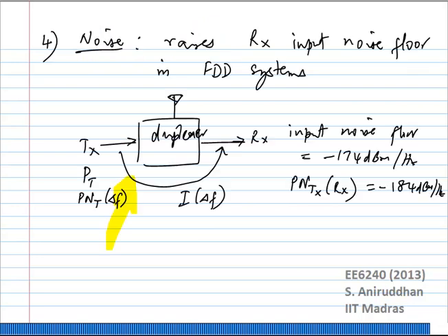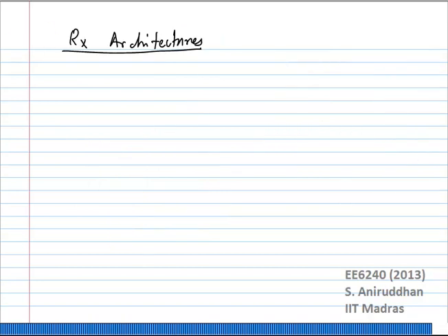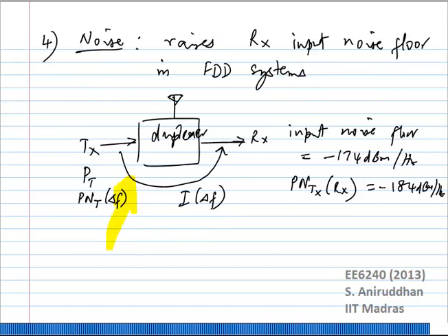Sorry, one last thing. I think we did cover this. The TX noise, of course, it will still be an issue, because what you transmit from one antenna can be received at the other antenna. Correct, but actually, normally the duplexer isolation will be much better than what you can get from one antenna to another, right? Because that will just depend on the spacing between the antennas. Whereas this one is like a filter which filters out most of the signal in the TX band.